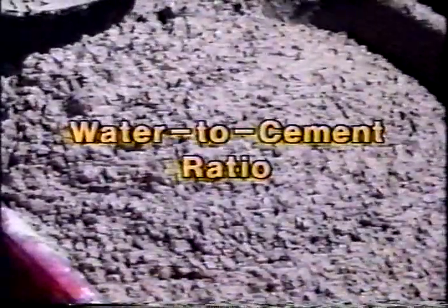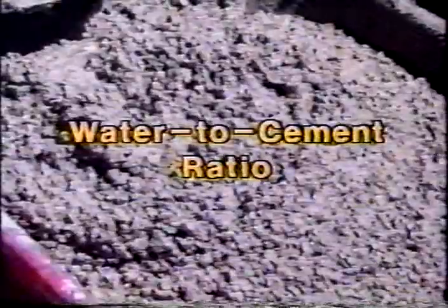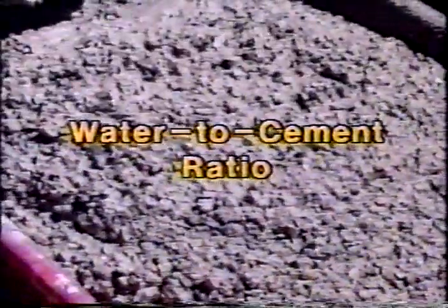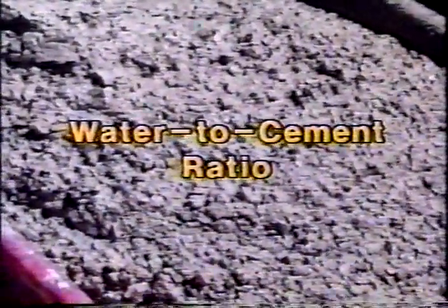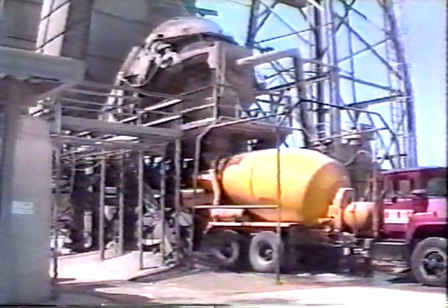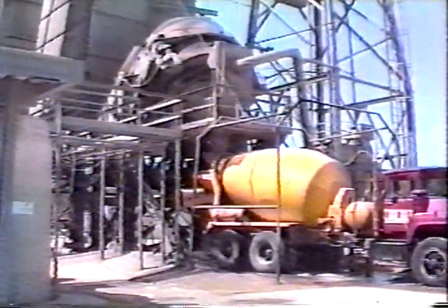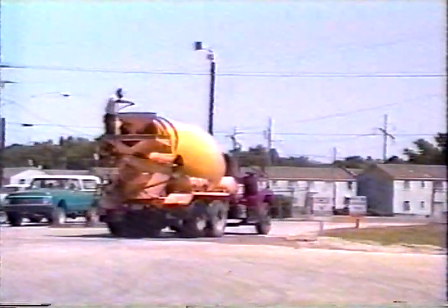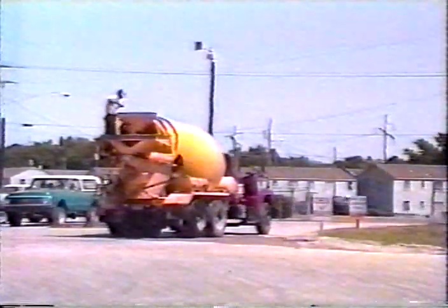It's well known that water-to-cement ratio is an important factor in controlling concrete quality. If the cement and/or water contents of as-delivered concrete are changed for any reason, the concrete will have different properties than what it was designed to have. While the cement content of concrete is usually well controlled during batching at ready mix plants, the water content is subject to change. Extra water may be introduced into concrete as wash water in the mixing truck or added by the truck driver as the mix stiffens.